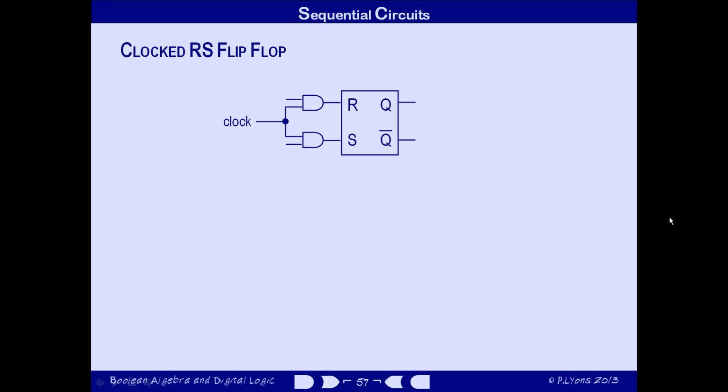If you review the truth table for an AND gate, you'll see that if you treat either of the inputs as a control input, then the output of the AND gate is false when that control input is a low voltage, and the output of the AND gate is equal to the other input when the control input is high. In other words, the control signal allows the data signal through the AND gate when it's high, and it forces the output of the AND gate to be low when it's low.